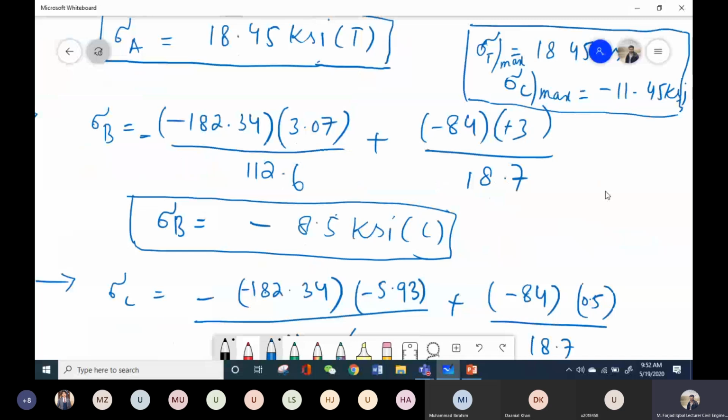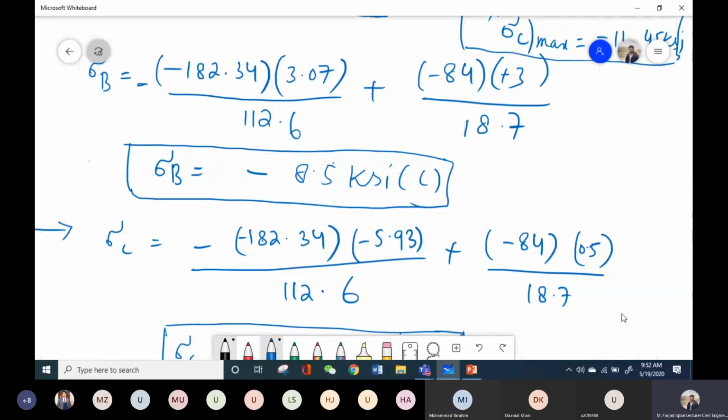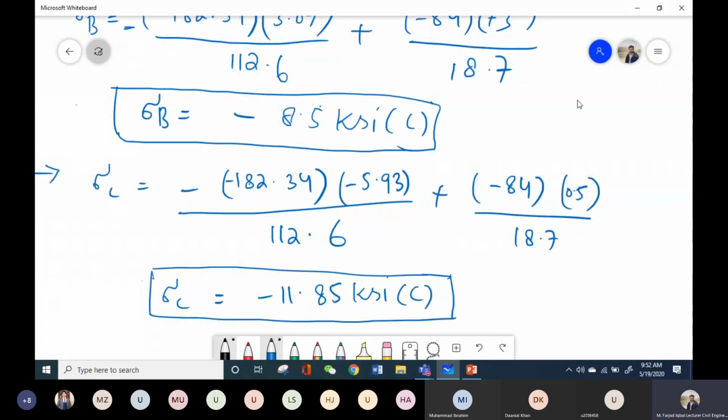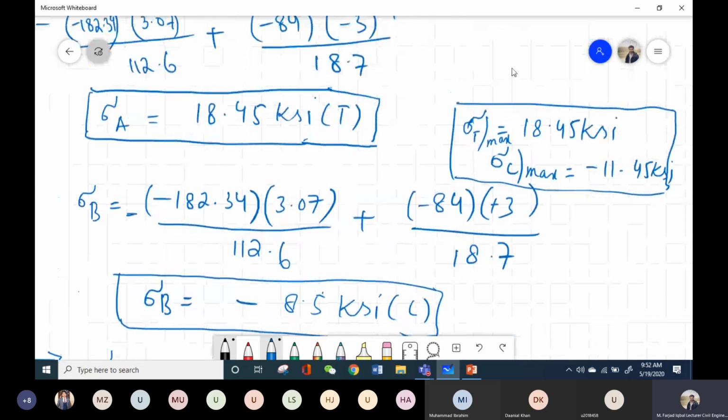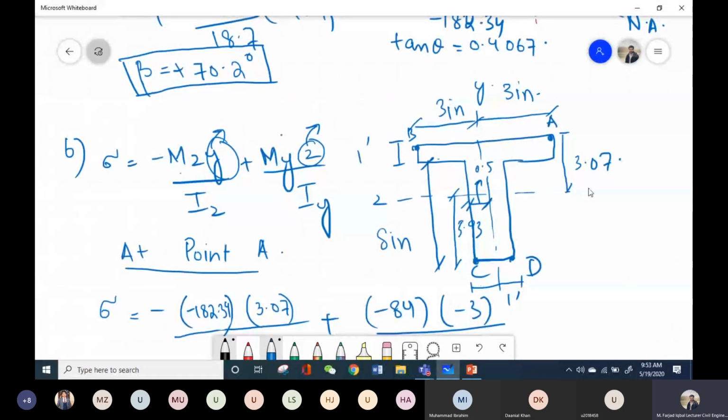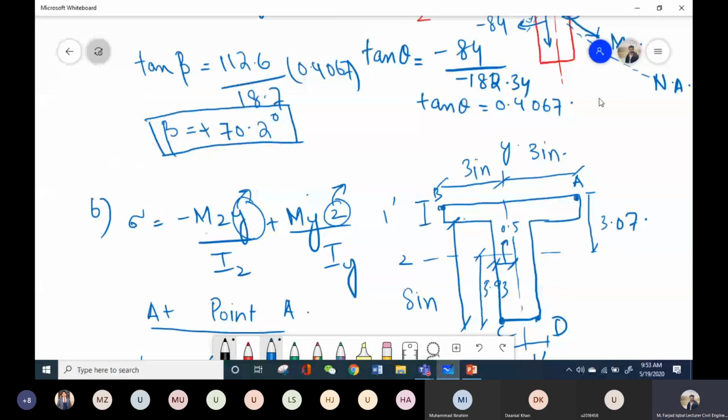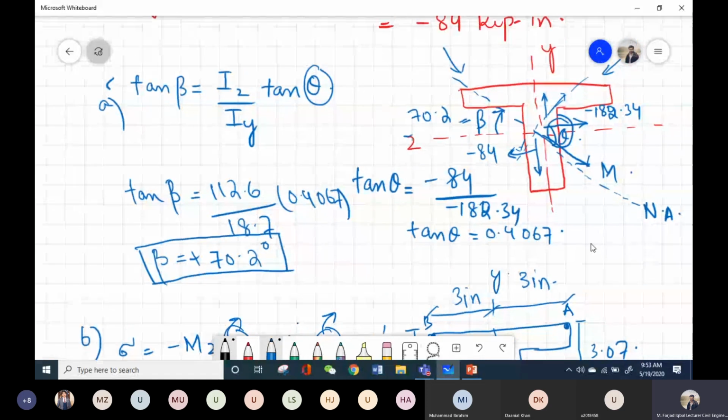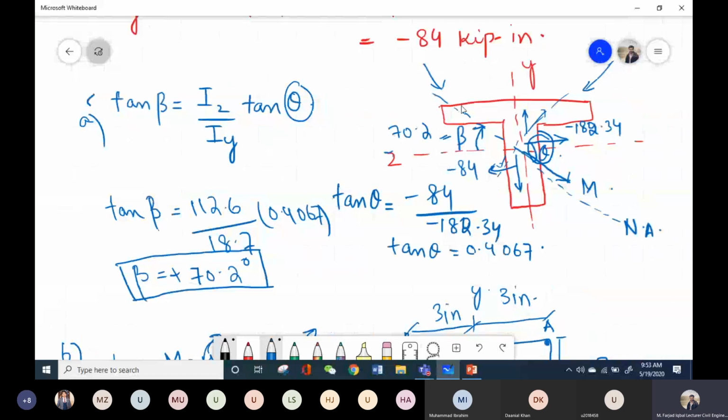So this basically concludes our topic for unsymmetrical bending of symmetrical section, and mostly you are going to see similar kind of problem. The only difference will be in the shape of the cross section or the type of loading. For example, you won't be getting the UDL in these cases, but mostly point loads, but you may get different kinds of inclination of where this load is acting. For example, the load can also act something like this. So you have to be very careful while figuring out the direction of the resulting bending moment.